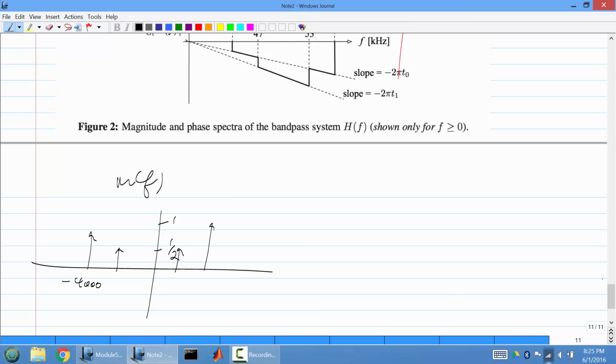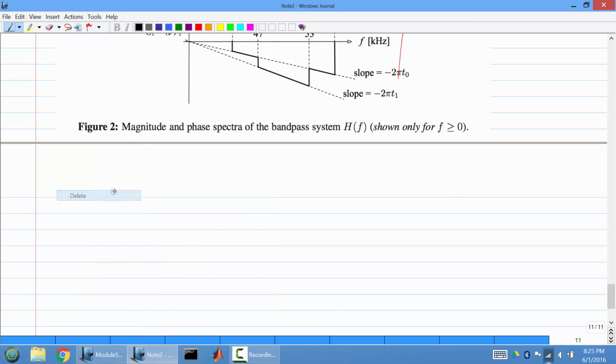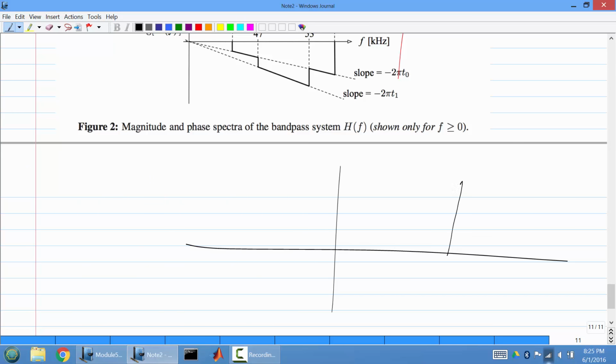Actually, no, it's the amplitude modulated signal, right? So sorry, let me cut that out. It's actually this guy here. So we had 1 at 50. So this was 2. This is 50. Oh, sorry. I have to draw the actual amplitude modulated spectrum, not the original message. So this is 46, 48, 52, 54. And I believe this was 1/4, 1/2, and 2. Okay, so that's what this is.